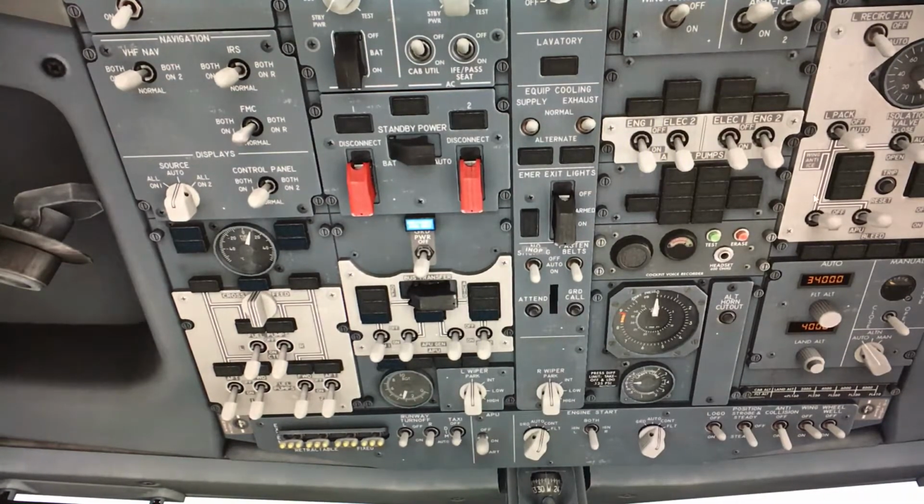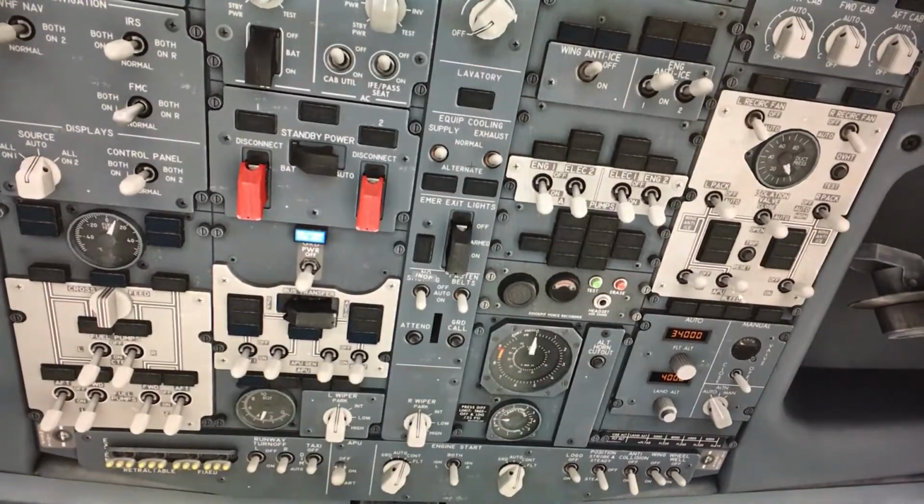But one more thing we have to do is switch the air feed, air conditioning compressor, cabin pressure compressor, air bleed, and de-ice for the left engine and right engine from APU to the actual engine. So we still have our cabin pressure running on the engine bleed instead of the APU bleed, because we just turned off the APU. Alright, once that is set, we're good to take off.